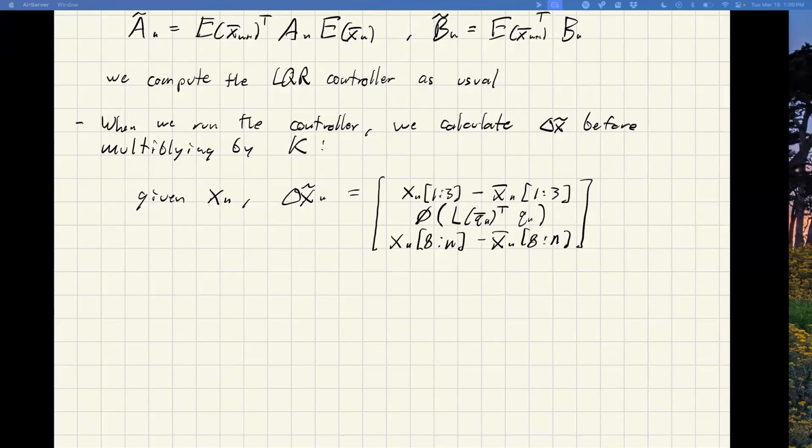And just as a note, we can actually use any 3-parameter phi representation we like. If you were a masochist, you could use Euler angles. I don't recommend it. But other good choices would be axis-angle vectors, which we talked about, or Gibbs vectors, modified Rodrigues parameters. Take your pick. Those are all perfectly fine choices.